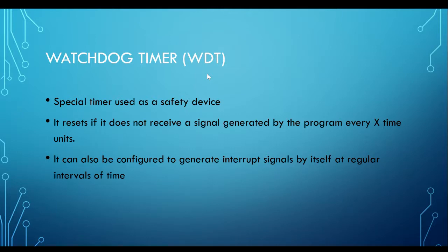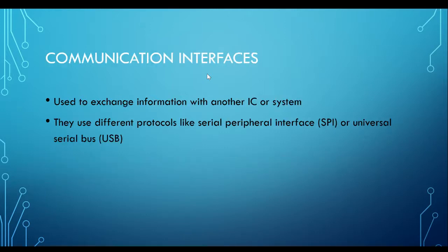Your watchdog timer will be able to help the CPU reload the reset address, and the CPU will go into the reset address to start all over again. This is very important because a lot of times you cannot go to the field and check every single embedded system that you have programmed. It's not feasible.